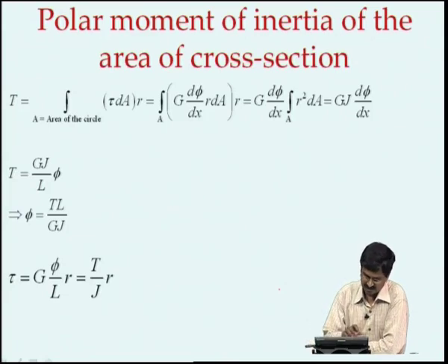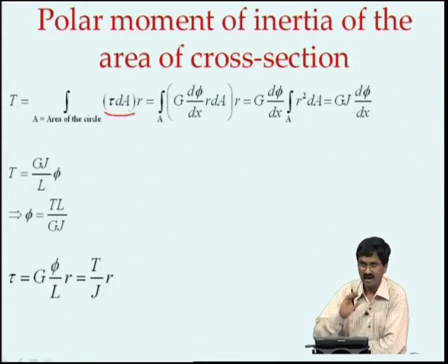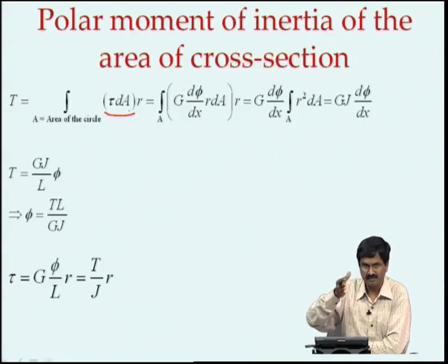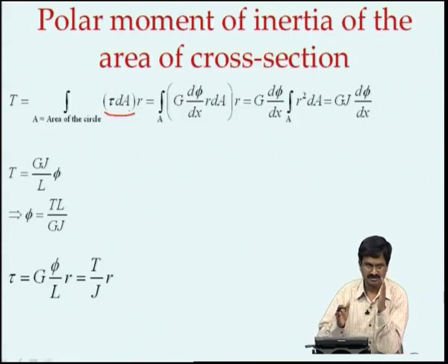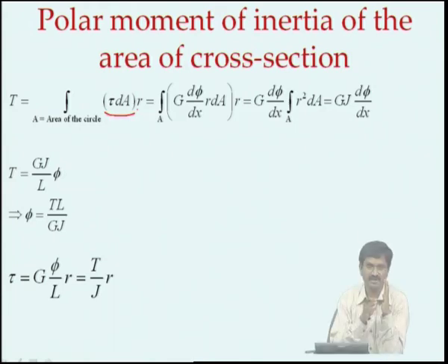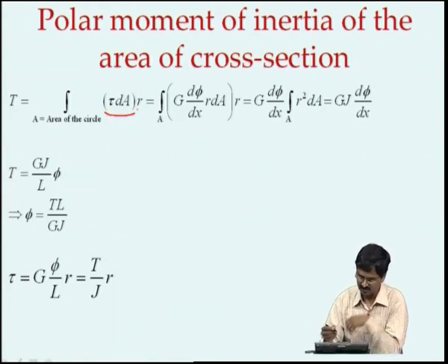That leads us to the equilibrium equation, which is: if I take the stress multiplied by area of cross section, I get a force that is acting parallel to it. So, I have this shaft surface and I have shear stress everywhere, I am multiplying the shear stress with the area and then integrating over the entire area by taking moment. So, I take a point at the center and I look at all the area and try to do that. So, let us sketch that.